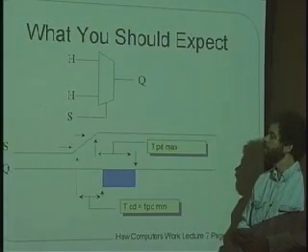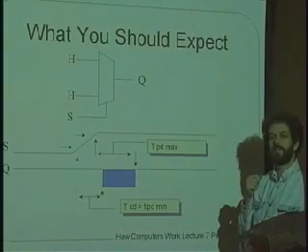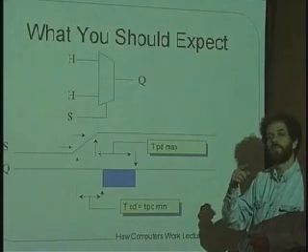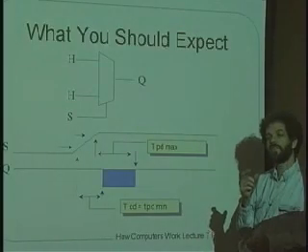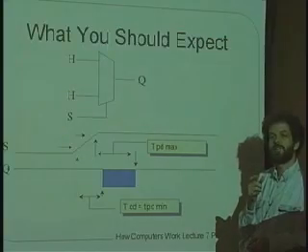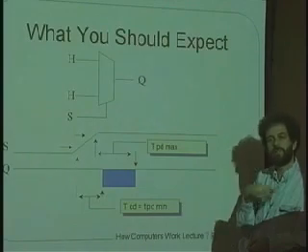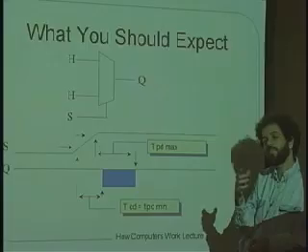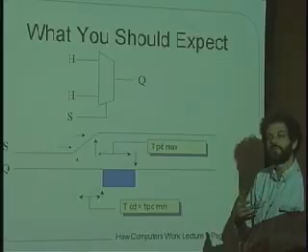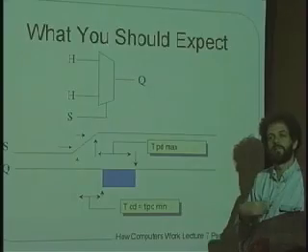That's an excellent question. In general, what we care about in our circuit is that the contamination doesn't get through too fast. Do you remember the hold time thing, right? We don't want the contamination to race around the loop before the hold time is up. So circuit designers in general worry about, will the contamination get to me too soon? And so the question is, what's the smallest amount of time for the contamination to start to race around the loop? One could say, what is the maximum amount of time too? One could measure that. But in general, it's not a measure that's very useful.